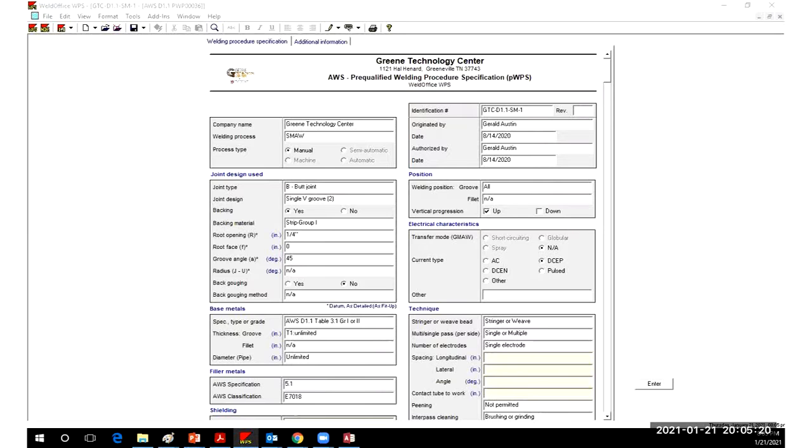So what you're saying is, if you produce a pre-qualified weld procedure and you test him on that, just say it's a stick electrode, and he goes out on the job site for another contractor, are you saying he's qualified to weld with their WPS? Yes.